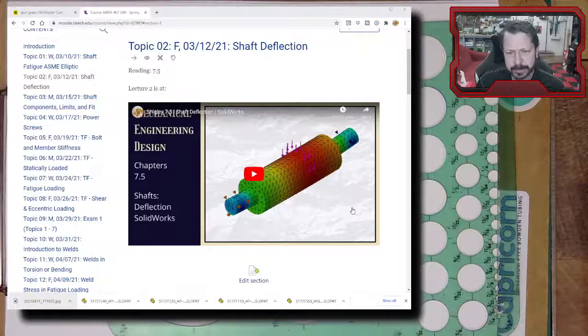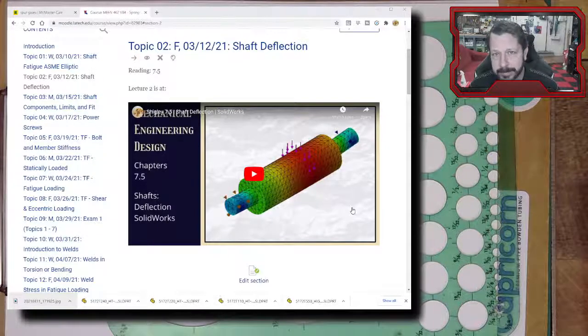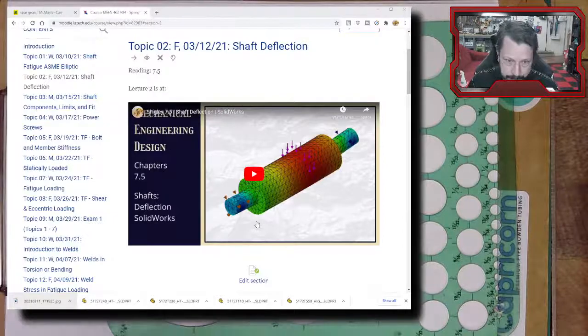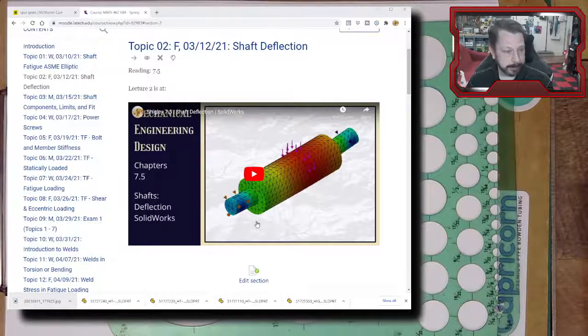In fact, if you do model those in, they're probably going to make your simulation a little susceptible to some continuity errors, unless you have a really fine mesh or you know how to create a variable mesh with finer mesh around those small details and coarser mesh elsewhere. So I would just leave them off. Even if they're not difficult to model in SolidWorks, I would leave them off for the meshing purpose and just use the gross geometry of the shaft.